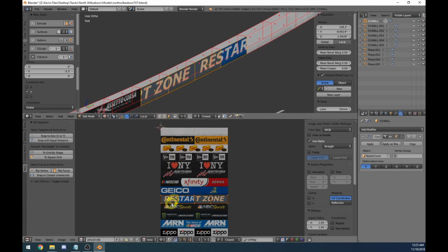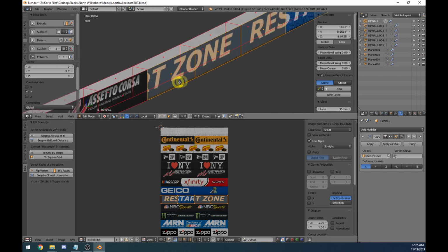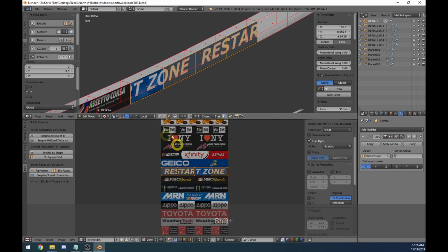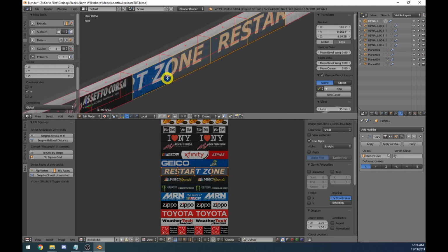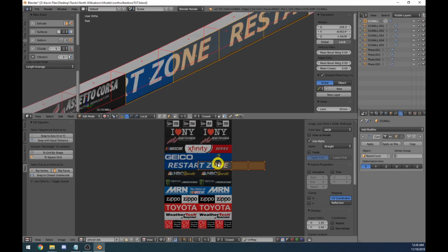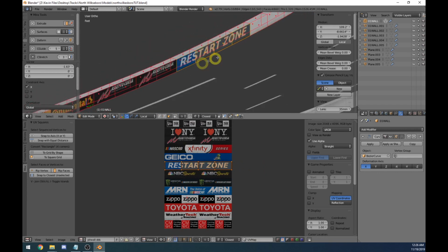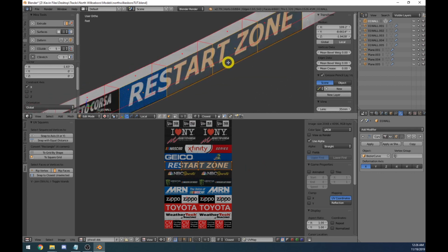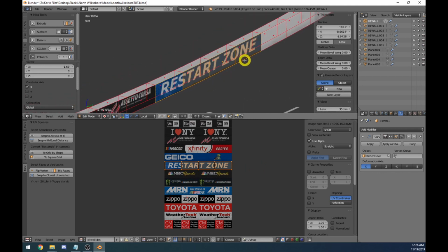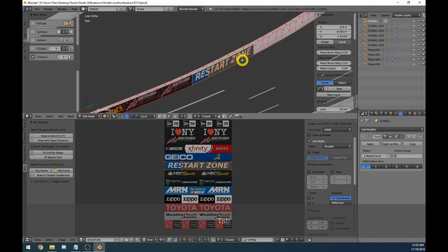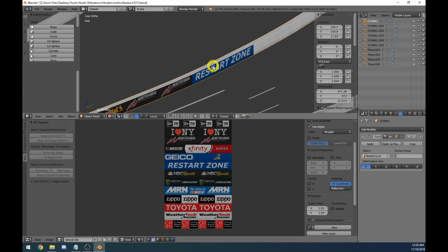That one didn't line up right actually, because that's between 2 sections. So what we could do here is, you see this piece here. We want to follow this active quad, move this on over, and that'll give us it to read properly. So that's just another way to use active quads, and that's why it's important to model in quads, or if you're converting something, to try to get it into quad mode by using the Alt-J command, because UV mapping and changing UV stuff like that is going to be a lot easier using quads.